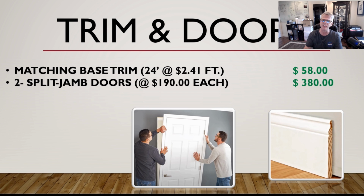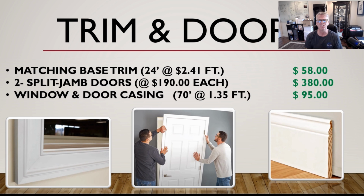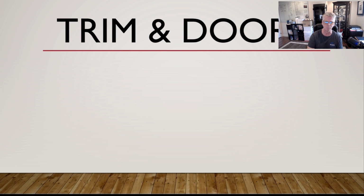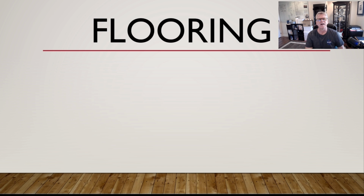You don't have to use split jam doors. If you can't find them in your area, you'll get flat jam doors. Standard flat jam doors with no casing, no trim on them. Set that, and then you'll need to go out and buy the window and door casing to go around that. And if you need to do that, you're going to need around 70 feet at $1.35 a foot for $95. Now, if you are getting the split jam doors, you will not need to buy any window and door casing because those doors come with it already applied. Grand total for the trim and doors, $533. And then we got the flooring.